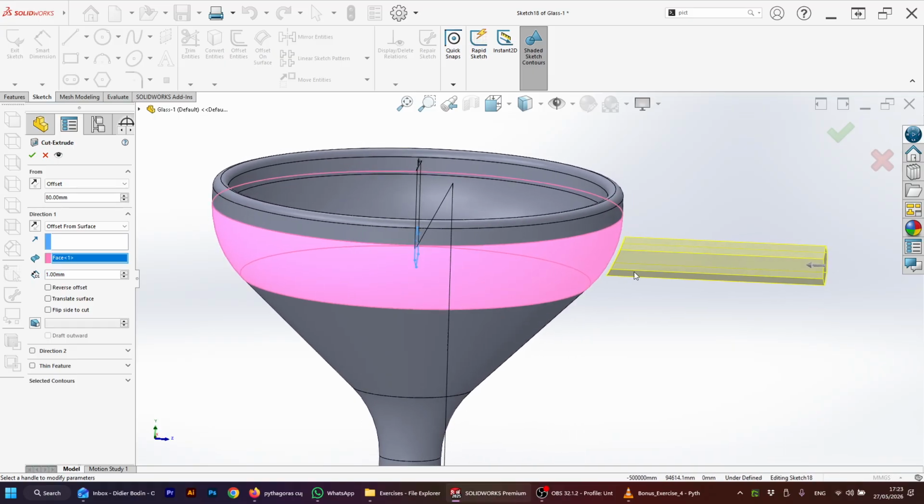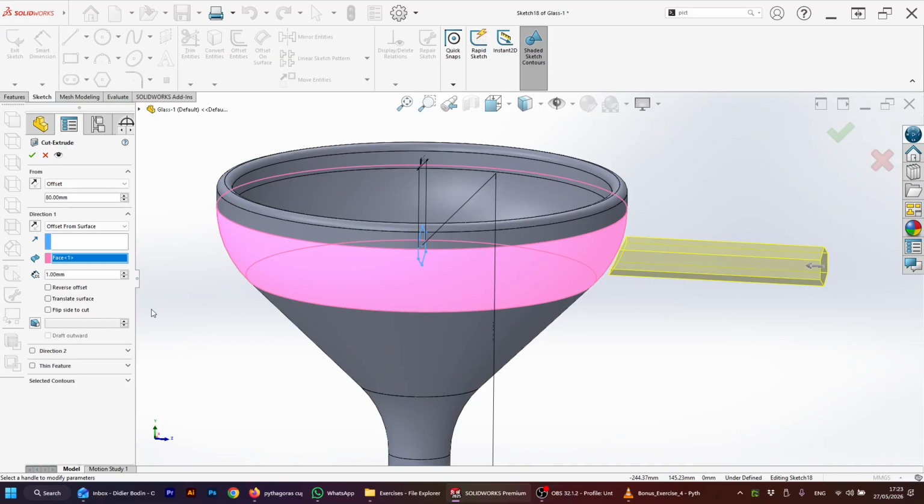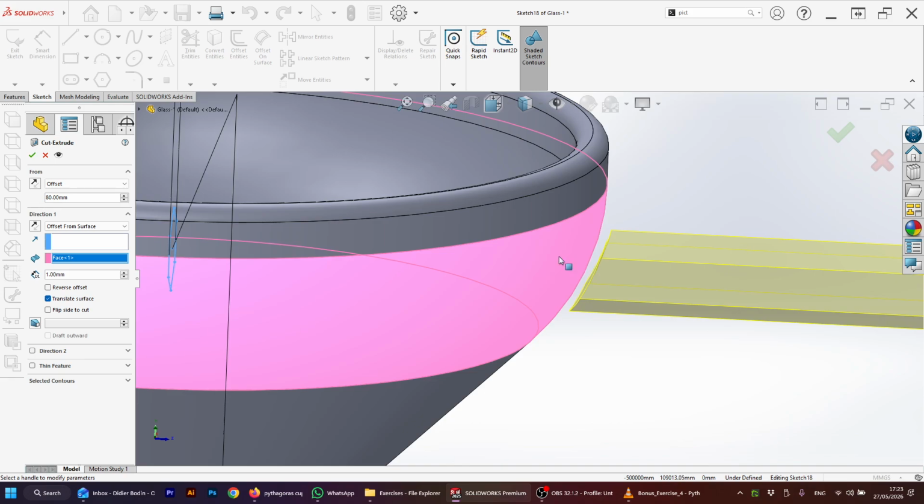And you can see it's trying to translate the shape of the cut. Here I need to play with the settings so that it actually enters into the plastic. Here I was outside. You can see there is a bit of white. It's not cutting into it. Reverse offset. All the settings on the left, that's where we play with the settings. Here is the depth until which I enter. So if I tell it 2 millimeter, you can see it's entering more. 1 is enough.